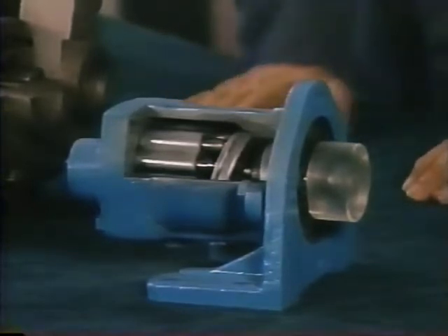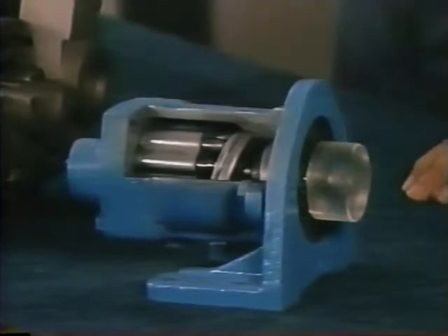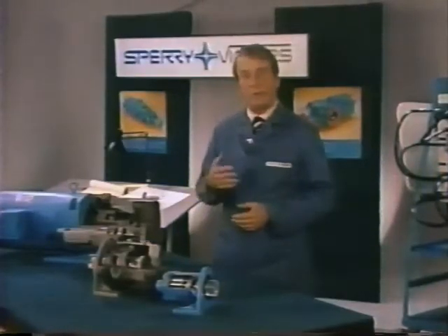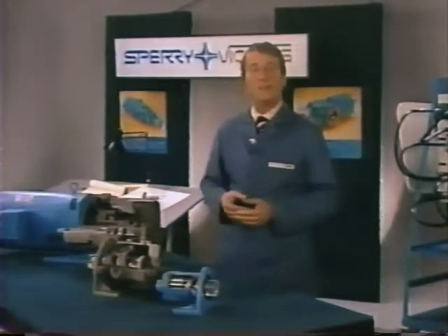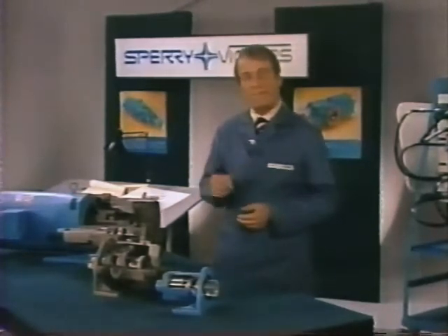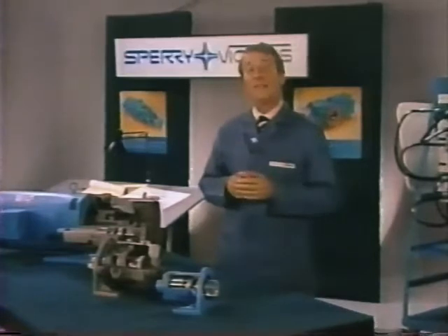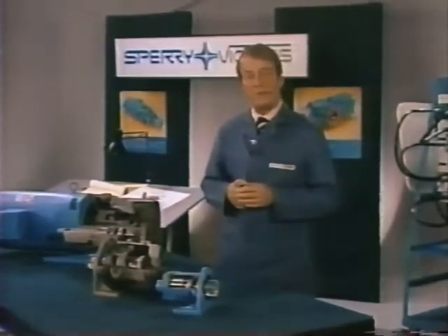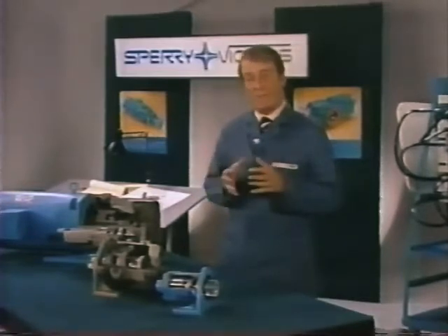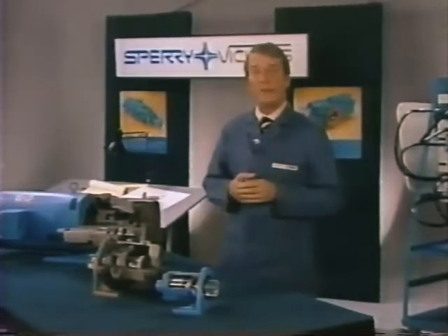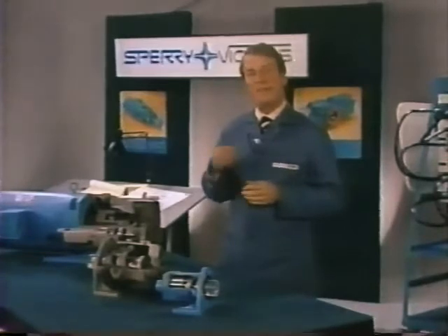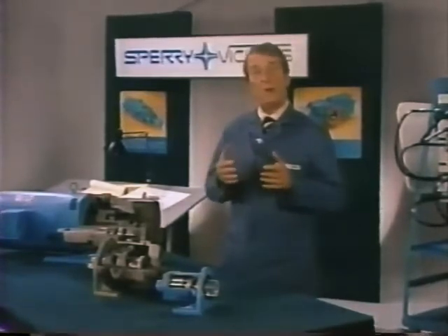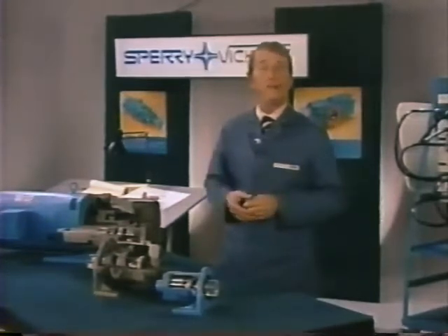Oil is discharged from the opposite port and is returned to tank at low pressure. Reversing oil flow to and from the motor would, of course, cause it to rotate in the opposite direction. Now that we have an understanding of how the pump and motor operate as individual units, let's try putting them together. If we could interconnect the ports of our cutaway units, we'd see that by merely moving the pump lever control, we could drive our motor fast or slow in either direction.